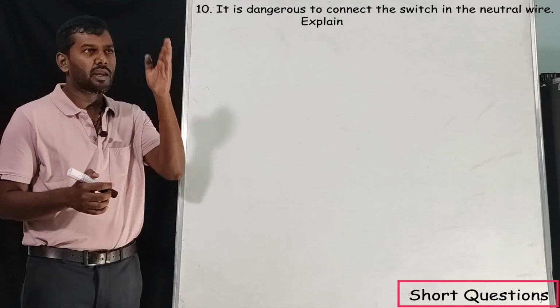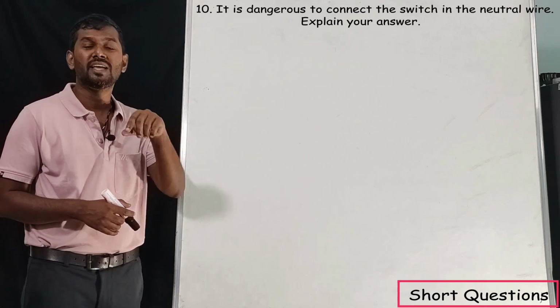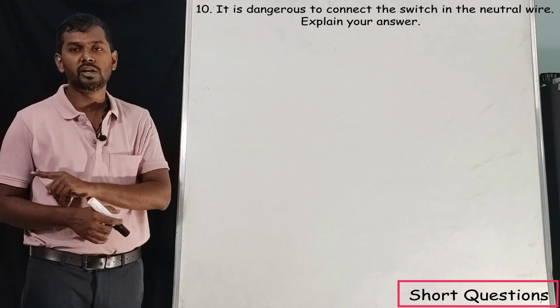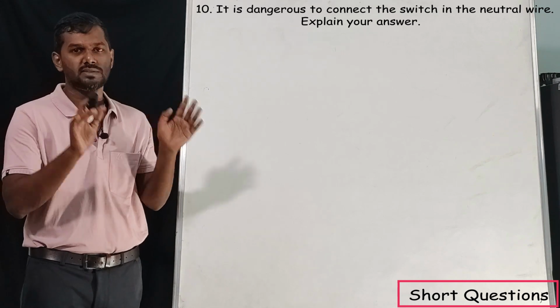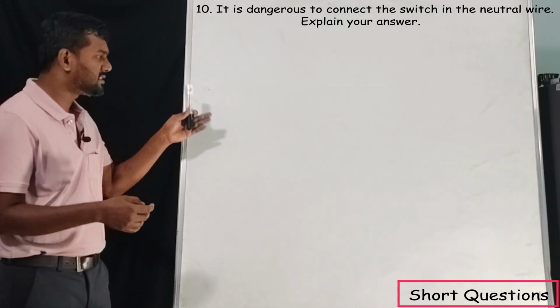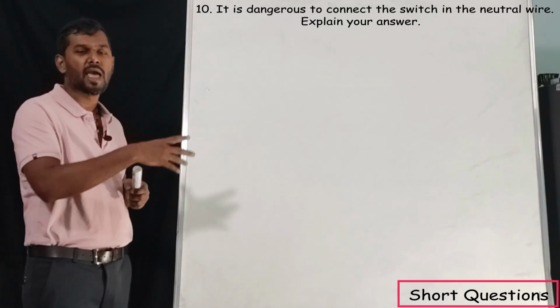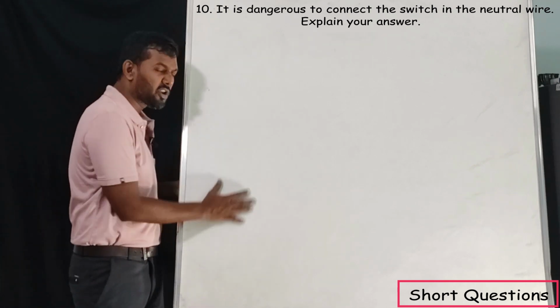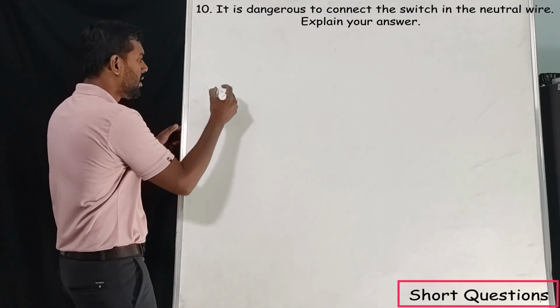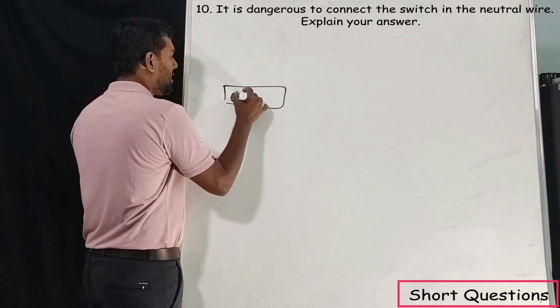Our next question: it is dangerous to connect a switch in neutral wire. Explain your answer. If they are asking it is dangerous to connect a fuse in a neutral wire or a switch in a neutral wire, the answer remains the same. See, for this question we can answer through the diagram, but in the exam the diagram is not necessary. For your understanding I am drawing the diagram. Assume this is the appliance